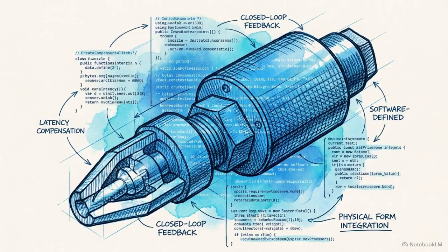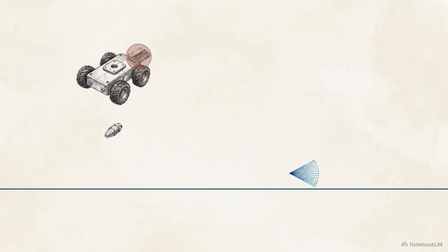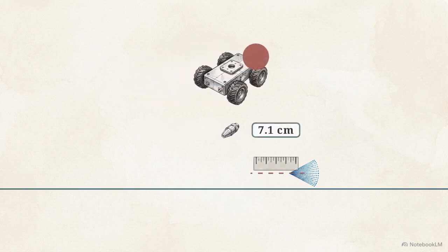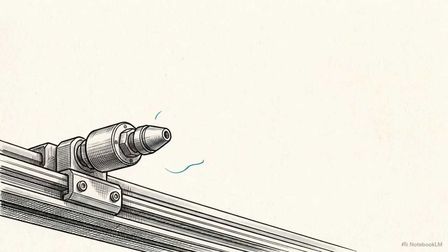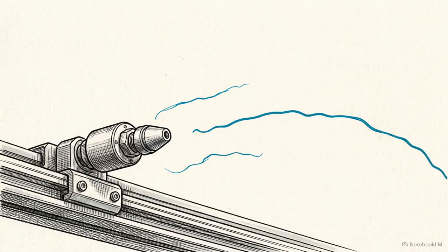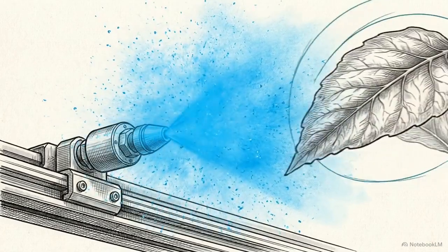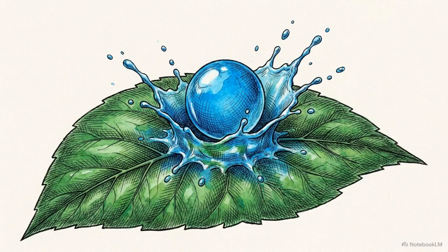The engineering solution to this displacement is software-defined closed-loop latency compensation. This schematic demonstrates how a closed-loop system dynamically calculates its own latency budget in real time, constantly pulling the chassis velocity sensors to project a vector ahead of the robot. By treating the 235 millisecond delay as a deliberate lead time, the predictive targeting system fires the PWM solenoids before the target aligns with the nozzle. The leaf and the chemical cone arrive at the same coordinate simultaneously.